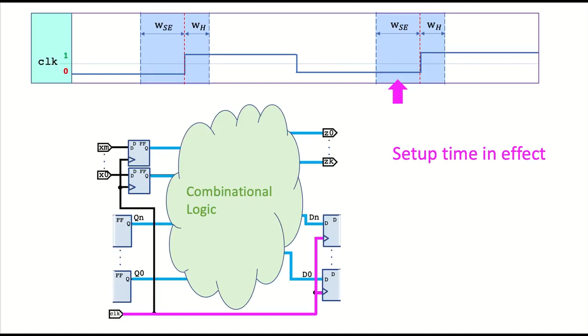Yes? So are the setup and hold times a physical feature of the flip-flop? Yes. The setup and hold times of a flip-flop are its properties. So you can go out and buy a cheap flip-flop and it'll have large hold and setup times, or if you want to buy a really expensive one that you can operate at high speed, it'll have smaller ones.